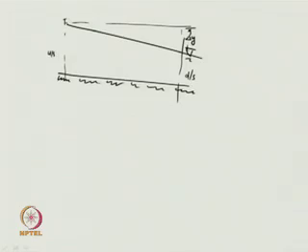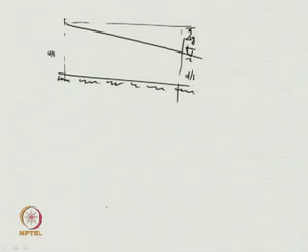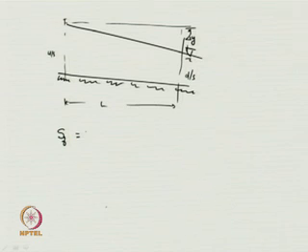You know that for uniform flow, water surface slope, bed slope or energy slope, all of them are approximately equal in general channels or in regular shaped channels. Right now, we have come into dealing with the natural streams where flood discharges occur. So, there is a difference in level of water surface at the upstream and downstream. That difference is given by del y. So, this del y by L, whatever is there, we can initially approximate this as energy slope.